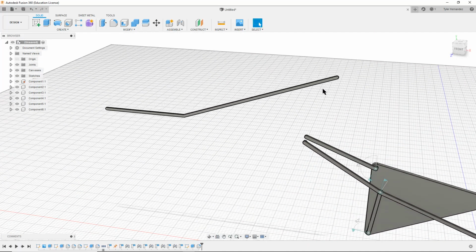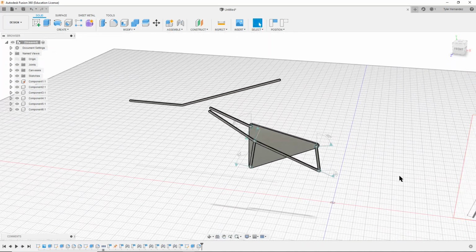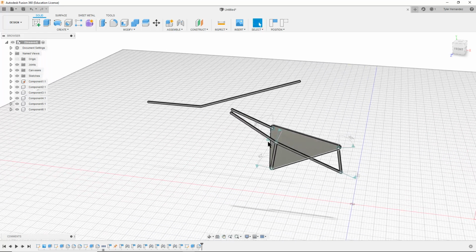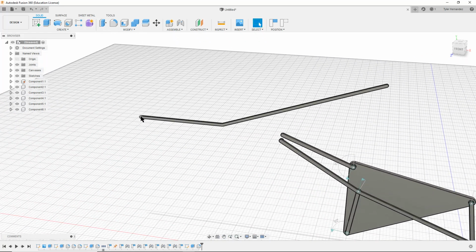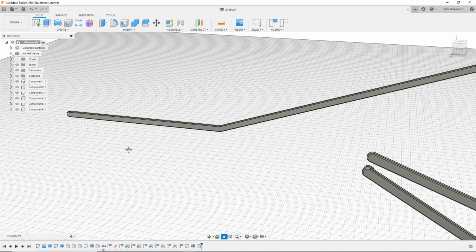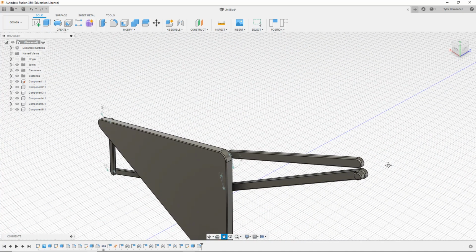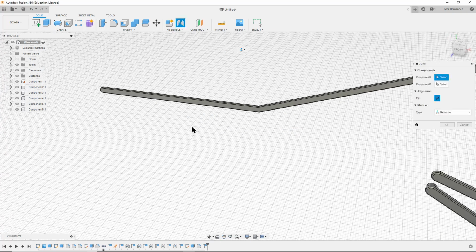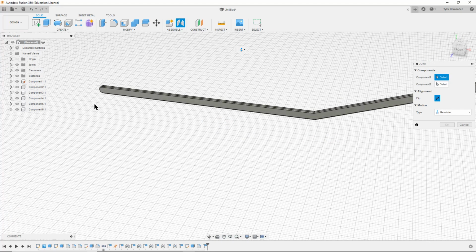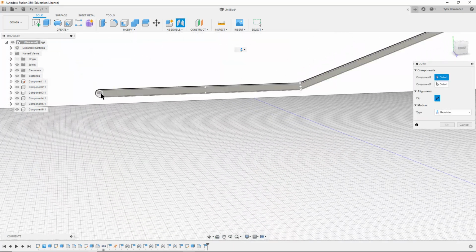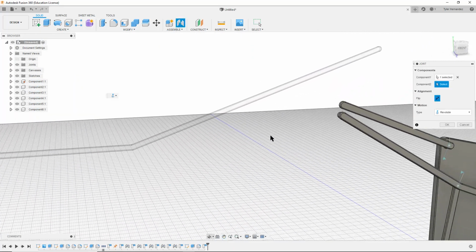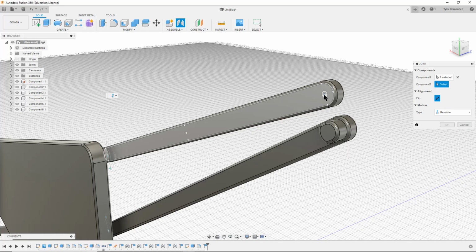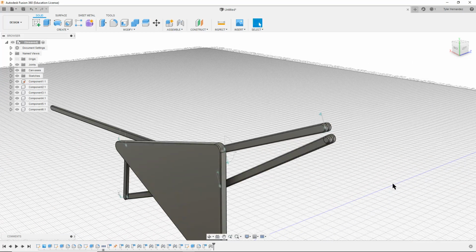So let's figure out the orientation we need first. If you look back at our drawing, the long leg sticks down. The shorter piece connects the two. So I actually need this side of this end to attach to the back right here. So I'm going to make my joint, capture position, select, what did I do? Select right there. Go back to my piece, rotate around, and select right there. And then I'll snap those pieces together and type OK.